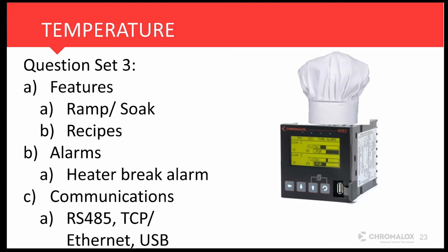So I would recommend, if that kind of scenario pops up, unless there's some crazy space restraint that they need just 1 quarter DIN controller, using 2 simpler controllers to achieve the effect of 1 more complicated one is usually the way to go, in my opinion.